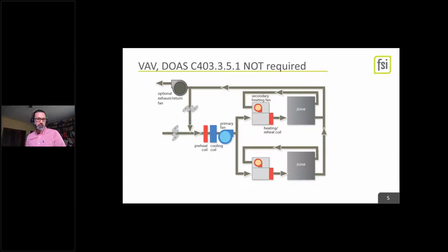So in a future-proofing way, we probably want to talk about moving things to heat pumps, even if you don't expressly have to under this version of the code, or if you could use one of those Washington exceptions in the next version of the code, you might still want to do it. There's externalities beyond just meeting the code right now. There's that future ratcheting down of BEPS targets that heat pumps will really help you over a gas system on an EUI target because they are 3 or 4 times more efficient.